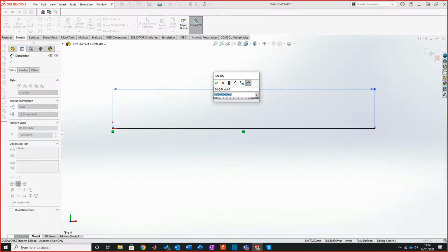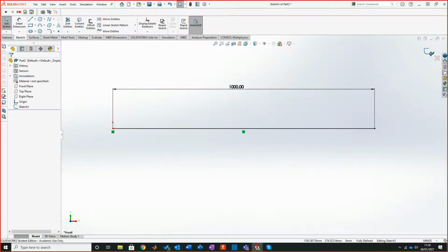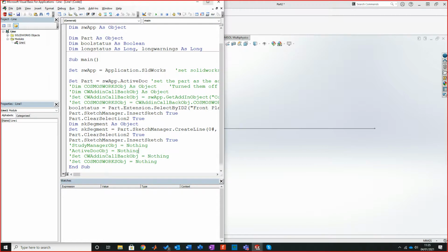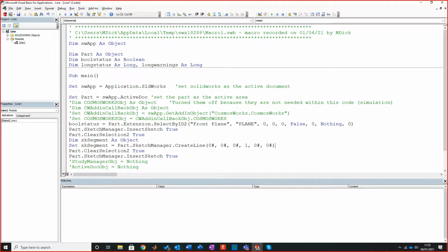So what does that tell you about the coding system? The only reason I do this is this catches students out on their assignment every single year. It is an absolute stump, and it really gets students annoyed every single year. I'll show you. I put in 1. It came back at 1,000 millimeters, exactly. It instantly tells you that the default units that this thing uses is meters. Always keep that in mind.